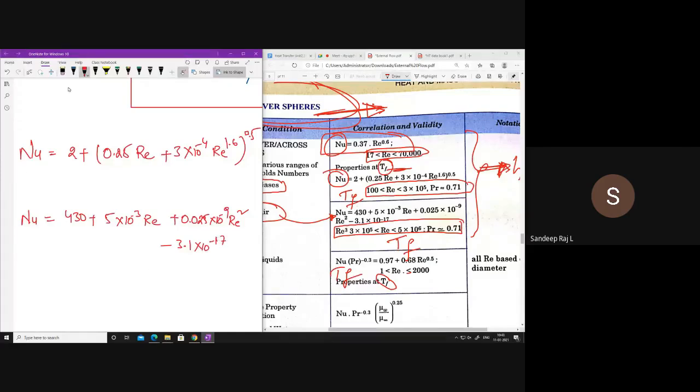These formulas also you can use. These two, solve for yourself. It is again kind of the same thing. You will have the Reynolds number on the right hand side, so substitute the Reynolds number into this, and on the left hand side again the same story, the h value will be unknown.